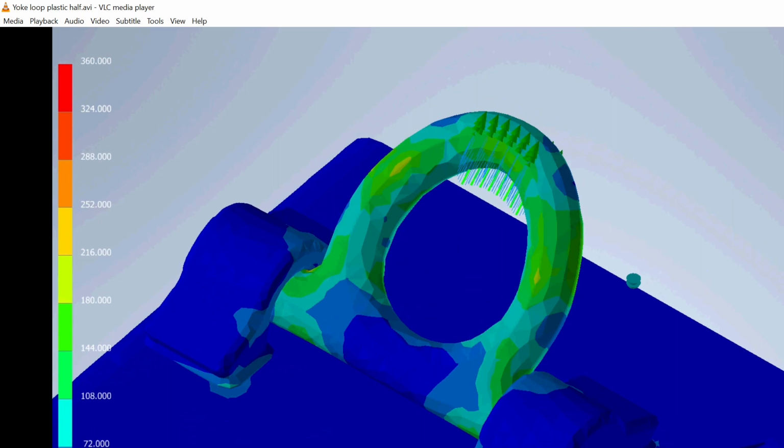the residual stresses are staying behind, so once the load is removed, the plastic deformations have an uneven stress area left behind, which could make the component sensitive to a different loading direction, because these residual stresses will sum up with the next loading cycle in case it's somehow different. And we can see very tiny amounts of residual stresses in the welded connection, which seems to be okay.